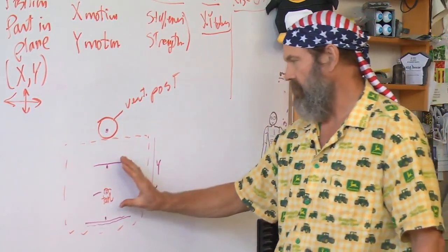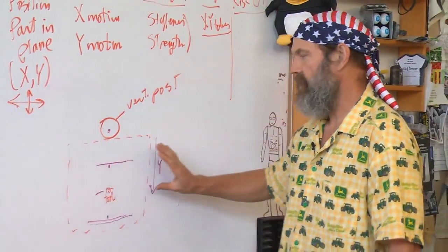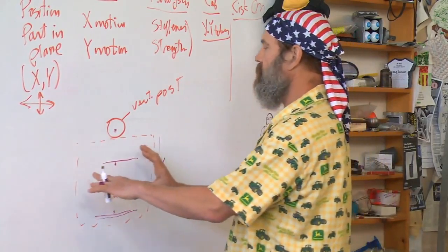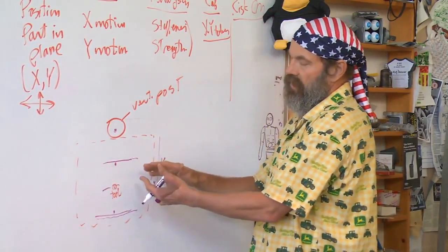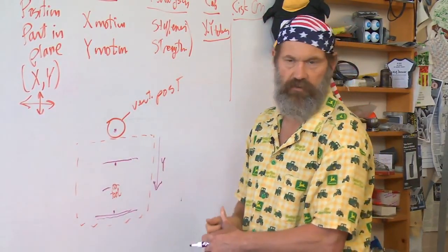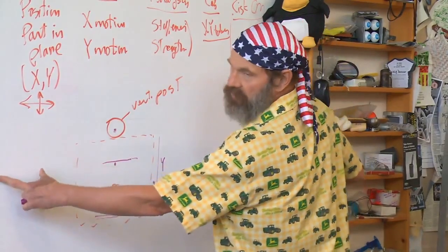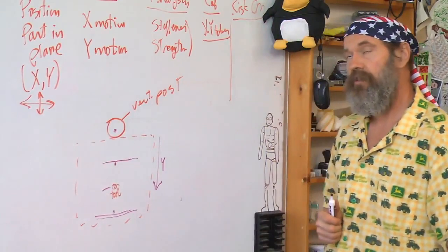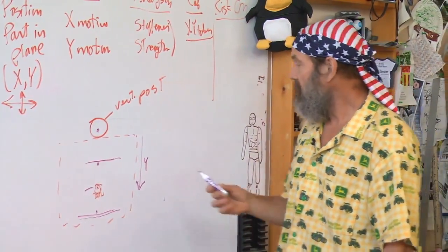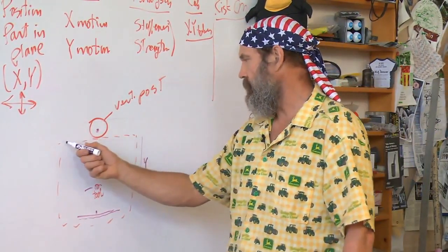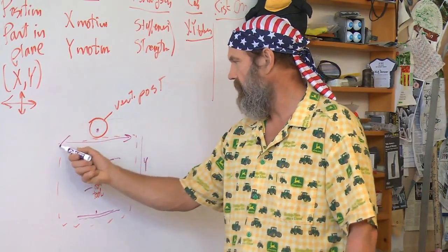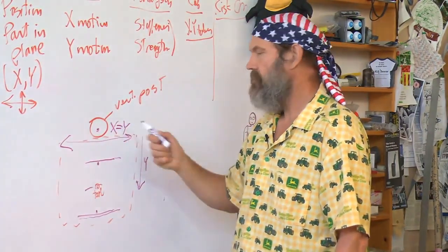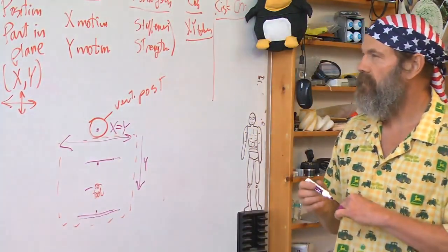The x direction is much more wide open in how far we can move. The question becomes how far you want to move without having to clamp and unclamp or refixture your part. If you made it really big, you might as well have a milling machine. So it seems reasonable that the x direction motion, to start anyway, is on the order of the y direction.